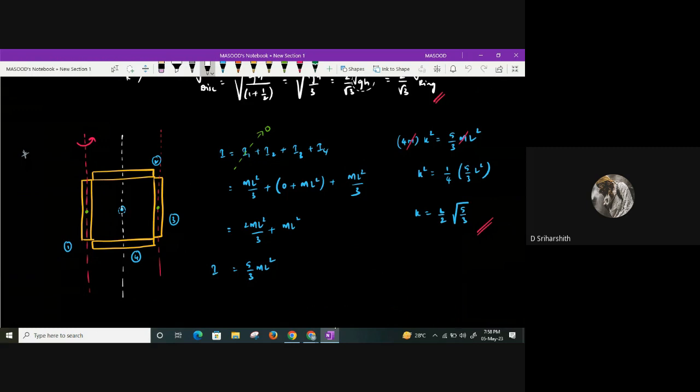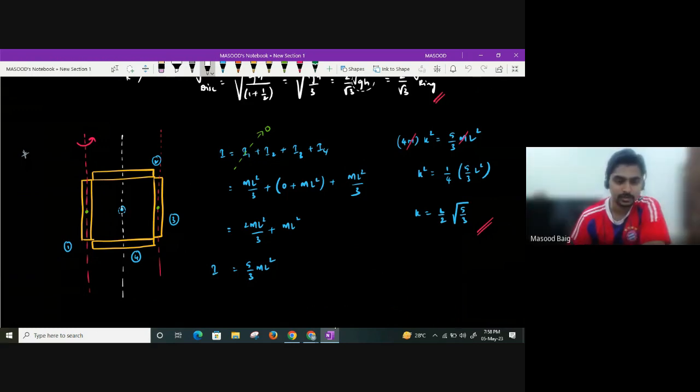No, because basically, how do you calculate the moment of inertia of any continuous object? We take small elemental masses. I want to find it about this particular axis, so I need to take elemental masses. This is one element of the rod. The moment of inertia dI will be dm into x square, and to calculate the overall moment of inertia, you perform integration.